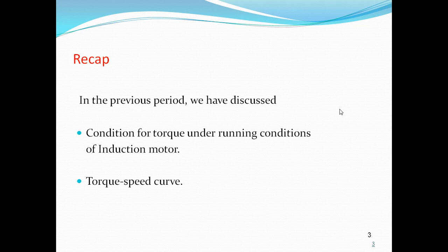From this we observed that when the speed is synchronous speed, that is Ns is equal to Nr, then slip is equal to 0 and torque is equal to 0. When the load increases slowly, the speed decreases and slip increases.